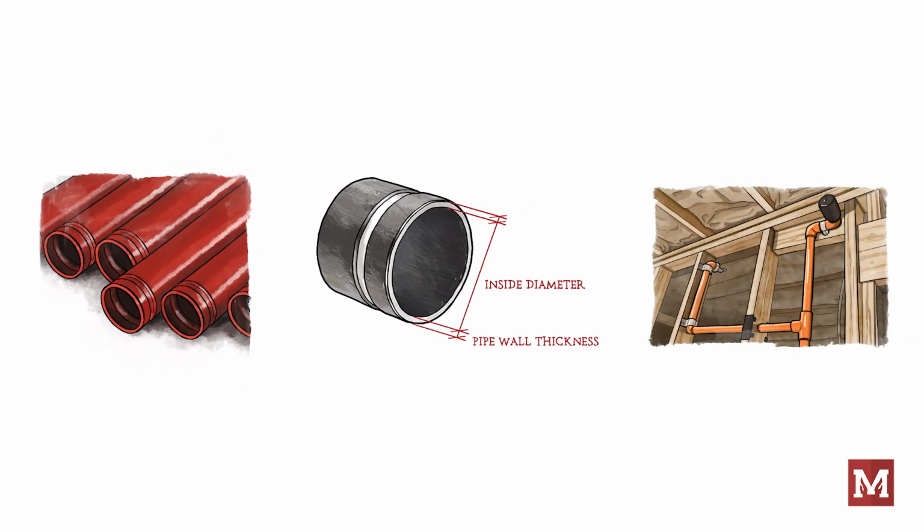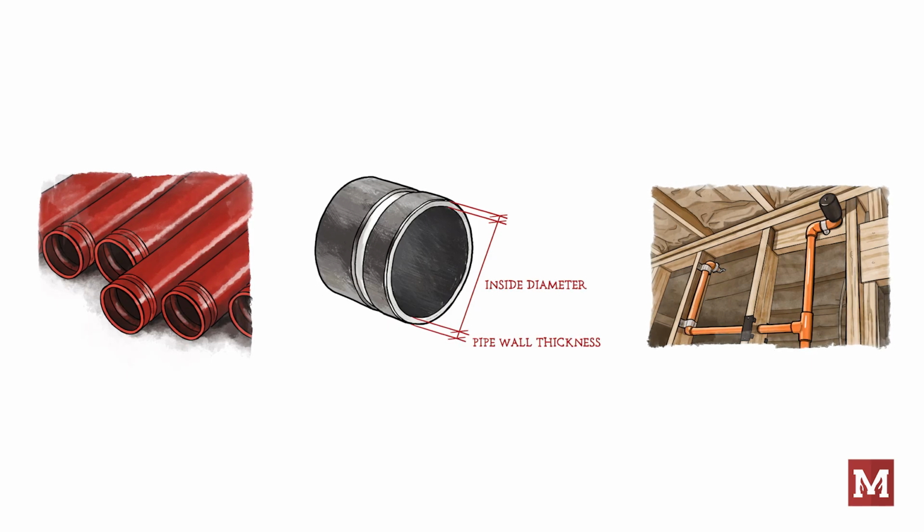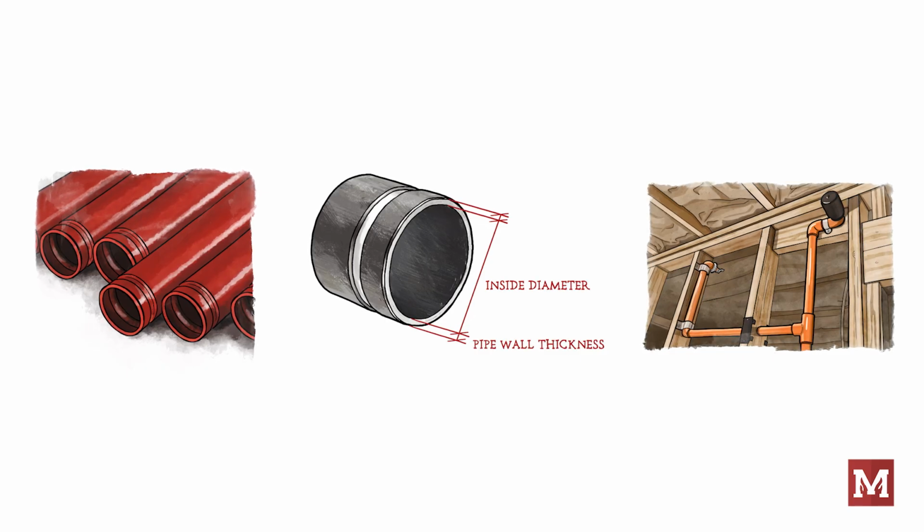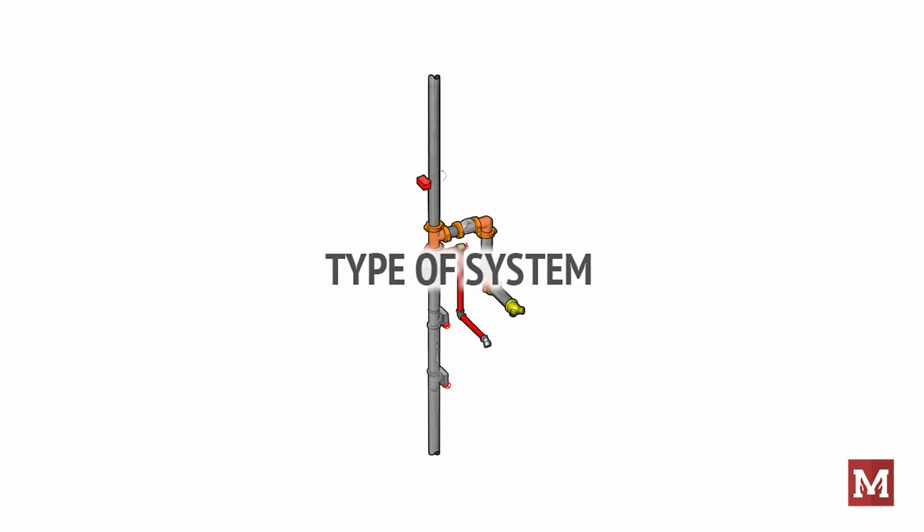Most 13R and 13D systems, and even light hazard systems, will use CPVC plastic pipe. Sometimes systems will use a combination of all of these. If you're sketching a system in the field to calculate it later, it's important to identify all of this ahead of time. We'd probably want to avoid just looking up at one point in the system and seeing a 4-inch cross main and assume all of it is 4-inch. We'd hate to miss a 6-inch cross main closer to the riser or a smaller main diameter further in the system.